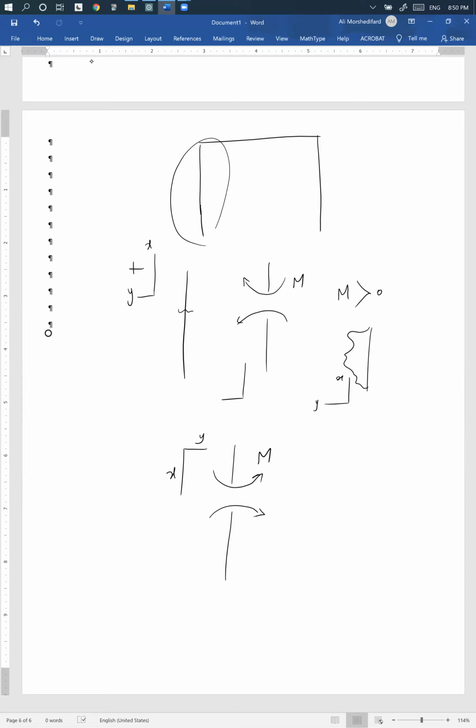But for the same structure, when you calculate, your moment turns out negative because your convention has changed. The problem is the same problem; you have only changed convention. Now the moment becomes negative.